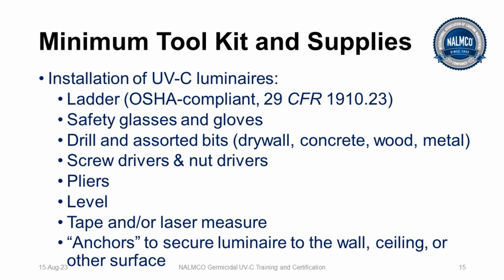For installation purposes, you need some kind of a drill and assorted bits: drywall, concrete, wood, metal. So you may not know what exactly you're hanging it to until you actually get there. Some plans are very good at identifying it, some are not. Screwdrivers, nut drivers, pliers, level, tape and or laser measure, and anchors to make sure that the UVC luminaire is secure to the wall, ceiling, or other surface.